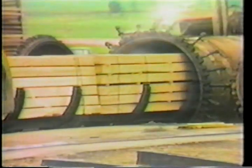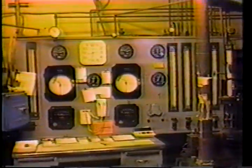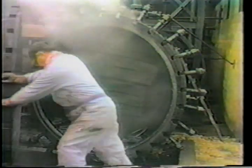The wood is then loaded on a tramway, capable of carrying 3,400 board feet, and taken into the treatment cylinder. While it's in the cylinder, the technician uses the control panels to check the treatment procedure. The wood is taken out of the cylinder. In good treating plant operations, easily treated woods and resistant woods are not included in the same package.